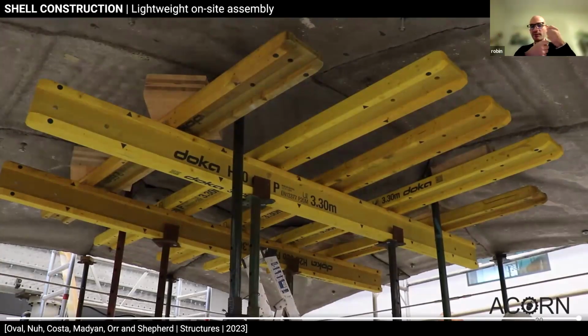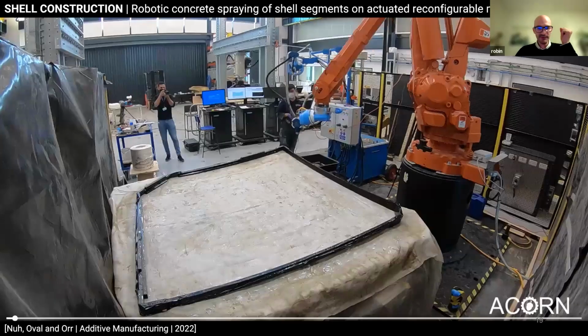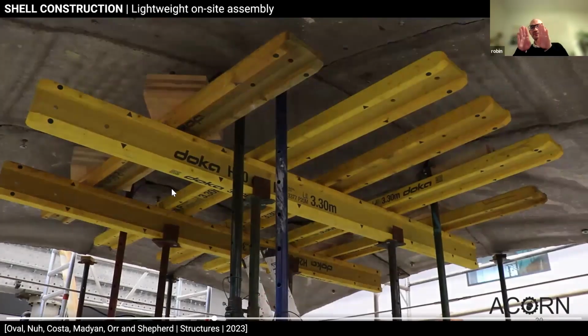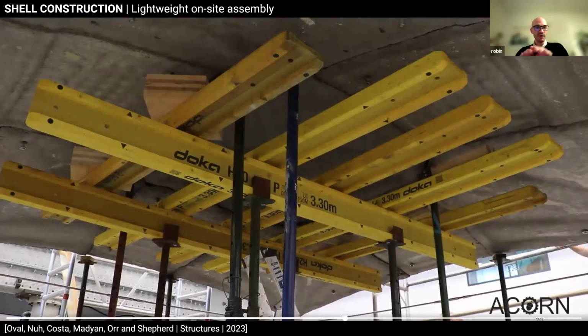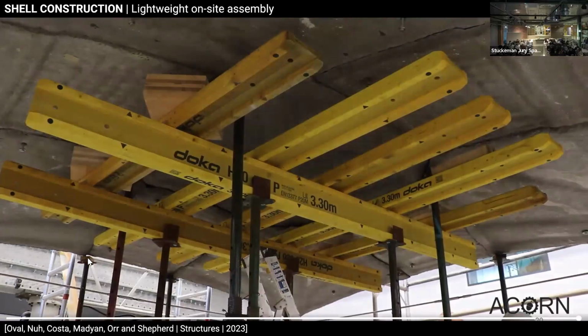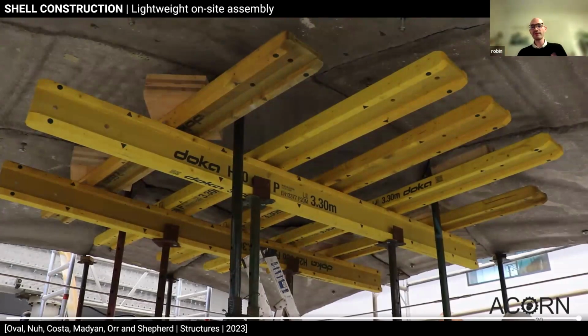And then we were just lowering down, let me replay this, lowering down the props until the gaps between the modules would close, and until the props, like the one you can see at the back on the left, would actually be loose. And that's when we went from modules to a set of elements that work in shell action and are all thrusting against each other.